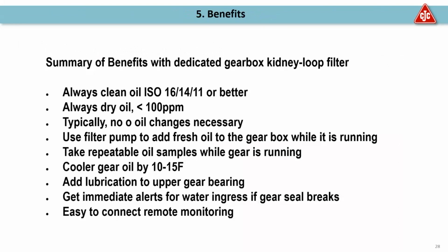So as a summary of benefits with a dedicated gearbox kidney loop filter, you can always clean your oil to an ISO 16/14/11 or better. Your oil will always be dry. There's typically no oil changes necessary. Gear oil doesn't really run that hot that it will oxidize much, so that you would have to change the oil for that reason. There's really no oil changes necessary if you keep your gear oil clean.